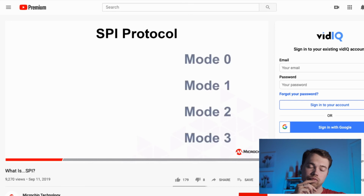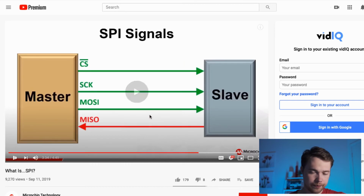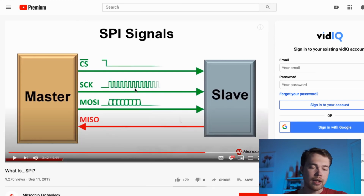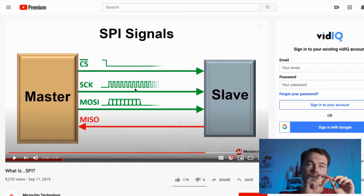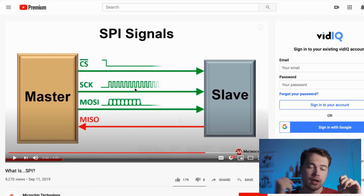SPI protocol defines 4 modes. Okay, so we're not interested in the modes, it's not that important, but we need this though. Top 3 signals, CS, SCK, and MOSI, are all generated by the SPI bus master. It's very important, like when 2 computers are talking to each other, to understand for each wire who is generating the signal and who is listening to the signal, right?